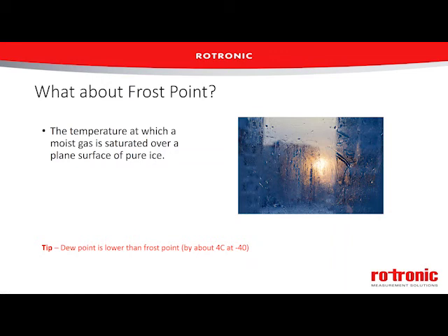Now, there's another term that's very similar to dew point temperature, and that's frost point. Frost point is a temperature again, and in this case, it's the temperature at which our moist gas is saturated over a surface of ice. And there's a key difference between frost point and dew point, and it's just the saturation over ice versus water. And you might say, well, isn't anything below the freezing point, 0 Celsius or 32 Fahrenheit, aren't we over ice at that point? And the answer is no.